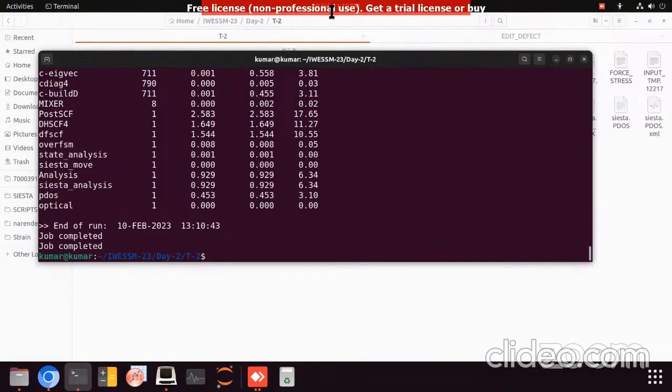Press ls. To plot the density of state, you can use the utility eig2dos. You can use another utility, fmpdos. So first, let me do it with eig2dos, or you can plot a file directly. When you add the PDOS flag in your FDF file, another file is created with the extension .dos.